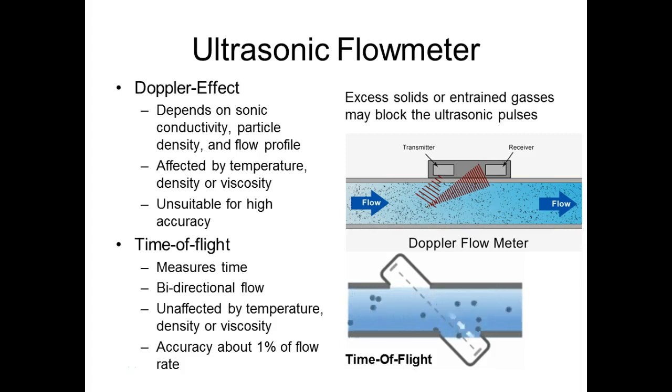It depends on sonic conductivity. The particles or the flow have to be able to carry sound, right? You understand, or pass it through. It's affected by temperature, density, and viscosity, unsuitable for high accuracy. So what we do is we shoot a beam down. The beam goes into the fluid. The fluid is in motion. It causes the sound to shift a little bit. And what these guys do is they measure that phase shift.